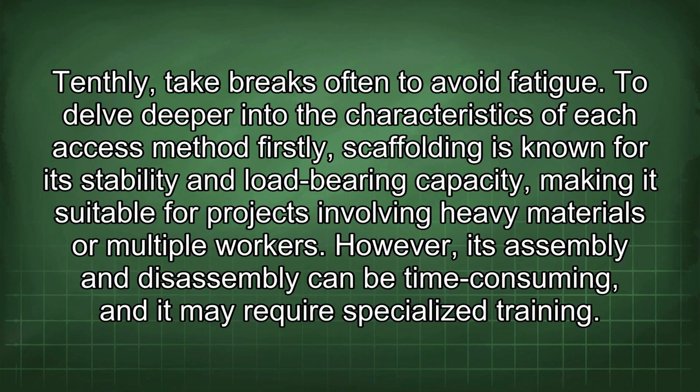To delve deeper into the characteristics of each access method, firstly, scaffolding is known for its stability and load-bearing capacity, making it suitable for projects involving heavy materials or multiple workers. However, its assembly and disassembly can be time-consuming and it may require specialized training.